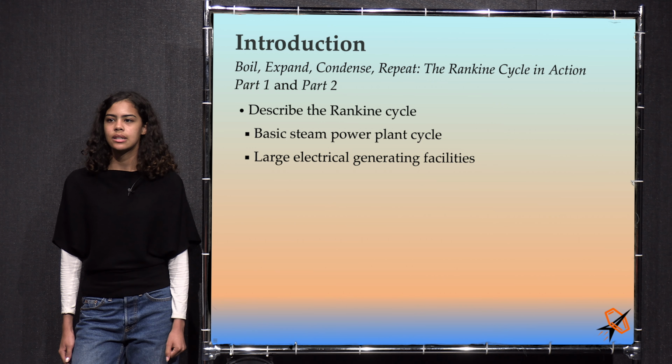The steam is now fully condensed into liquid water at point A. So now, the pump is only pumping liquid, which means it will use much less power and will survive much longer than a two-phase compressor. Delta H for the pump is V delta P. In addition, we have superheated the steam beyond the two-phase region, so that when it passes through the turbine, we are much closer to the edge of the two-phase region and have higher quality, which means that the erosion of the turbine blades will be much less.